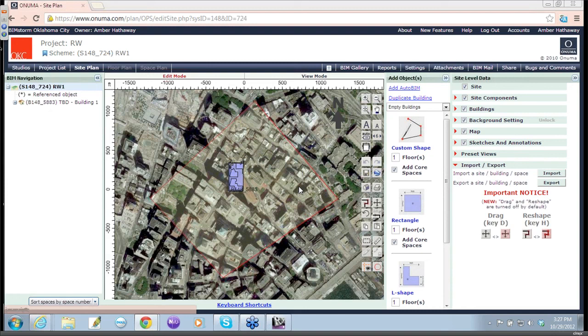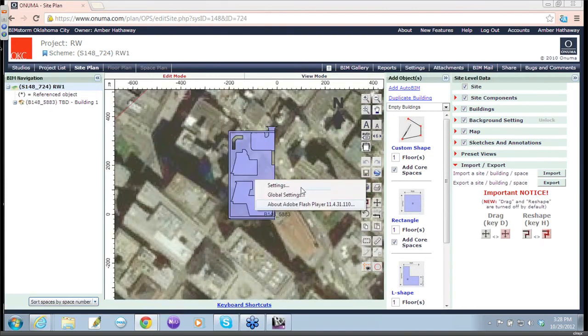Is that right? Yeah, when I come across that error, like I said, I'm not a super expert when it comes to Revit. I just know how to work with it within the terms of the Enuma system. And usually when I come across that error, if a room is not placed, it's because I placed it and then deleted it, or I tried to move it to a different floor, or I placed its information but didn't actually define its boundaries. There may be someone else who's more capable of explaining this, but let's go into some of the floors of this building.